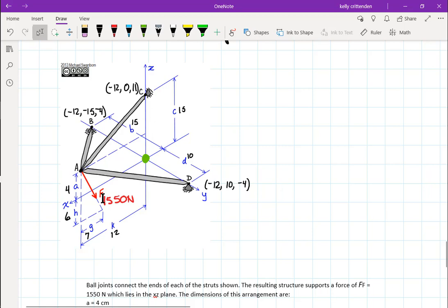Right? That's just a convenient point to measure from. So in this particular one, I would actually go in and make the origin here. And then for my numbers, I put in the X, Y, Z coordinates based on that new coordinate center